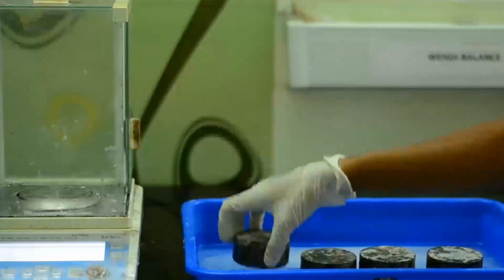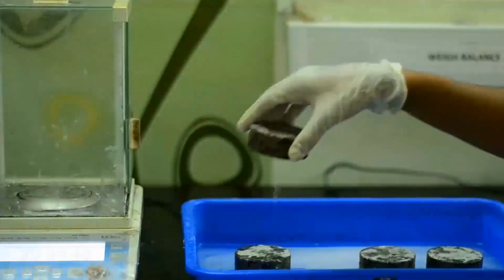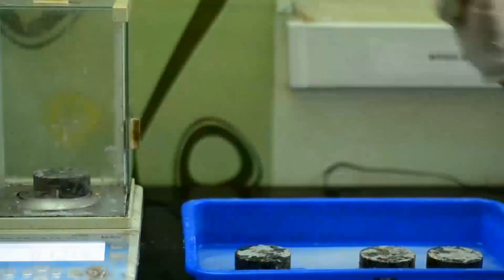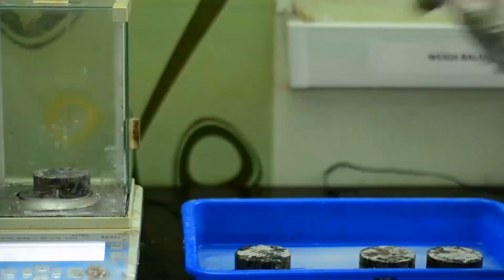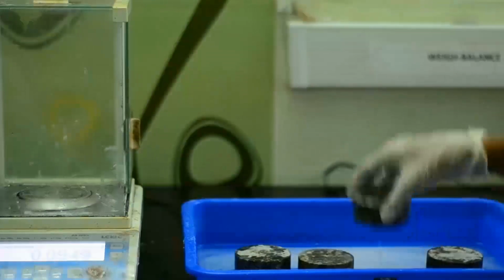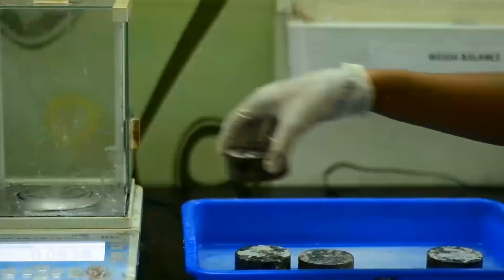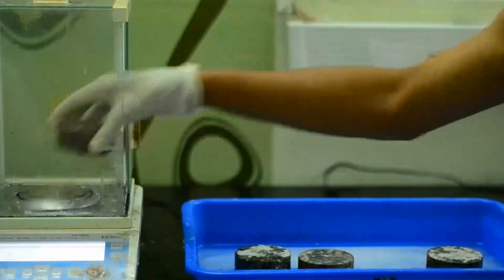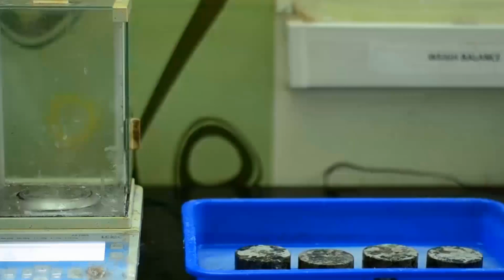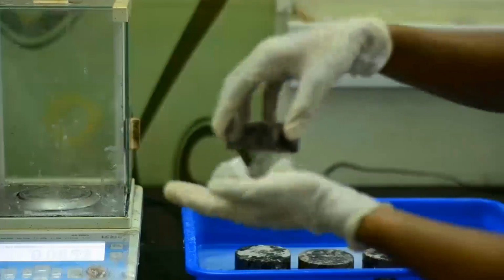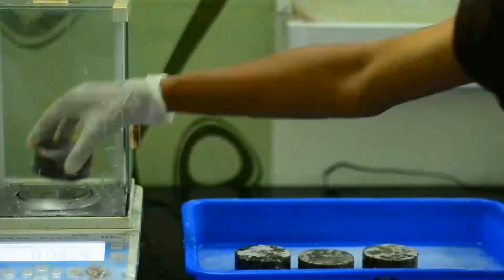Care must be taken to prevent dripping from one specimen onto the top of another while removing a specimen from the tray for weighing. The stopwatch should not be stopped during the weighing procedure. Record the mass of the specimen within 10 seconds of removal from the tray. Replace the specimens each time with the same test face on the base sticks. The saturation condition is attained when the weight of the specimen remains constant for a long time.